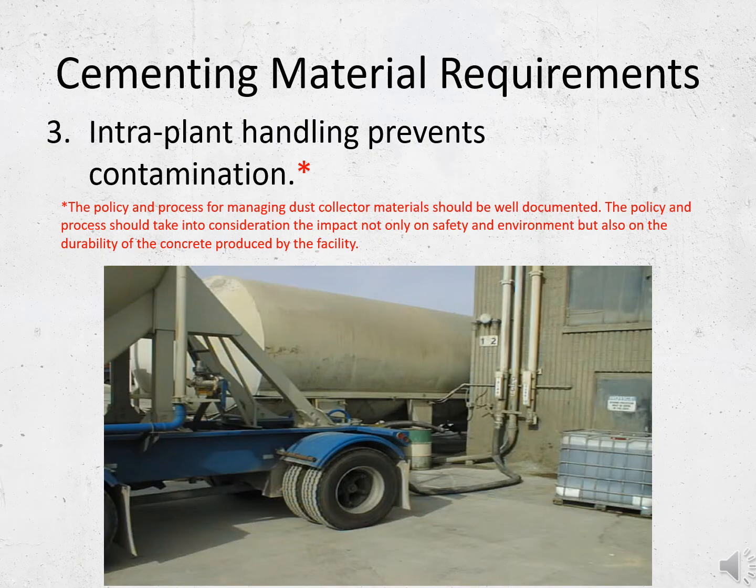There should also be a written policy in place to define the protocol for sweeping trailers when switching products hauled in a given pneumatic trailer to ensure that any cross-contamination is prevented, and that if it does occur, it's not to the extent of compromising the performance and durability of the concrete produced.